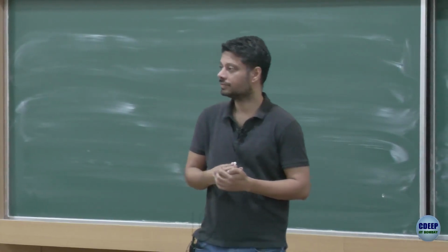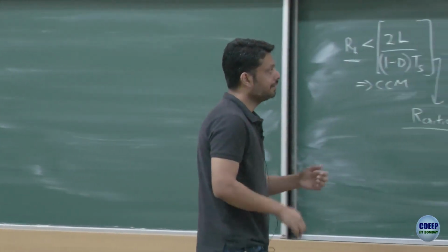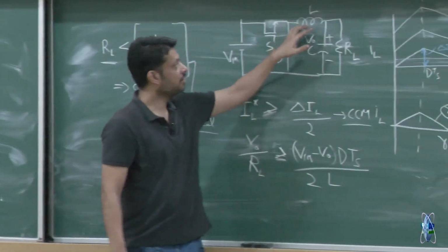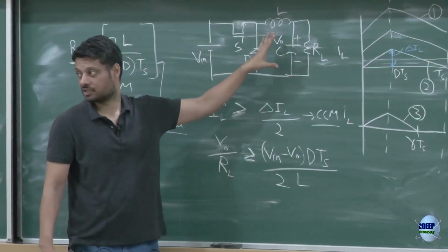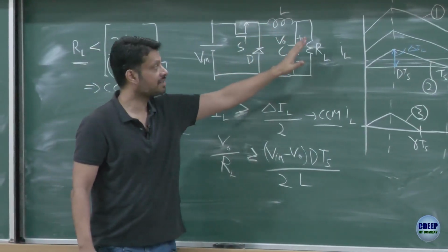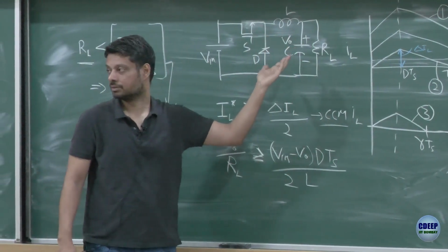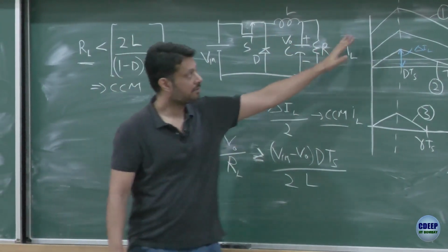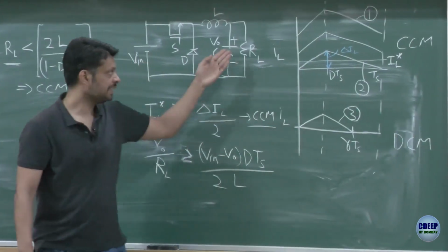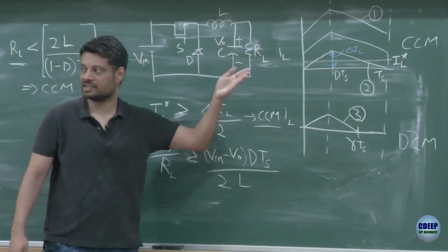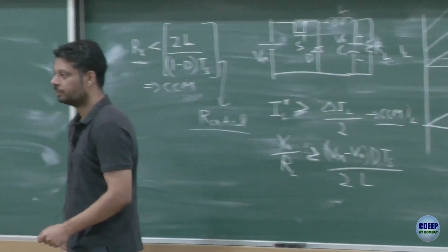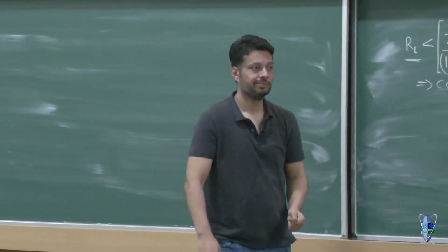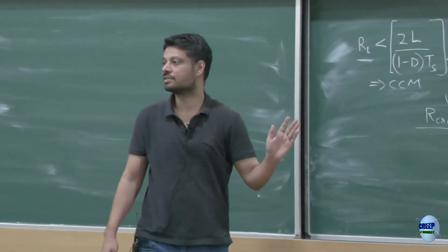No, that's what I am saying, right? Your converter is producing the voltage and the current is determined by the voltage. The voltage is constant from case 1 to case 2. You are changing the load resistance, current is changing accordingly. V by R. Any more questions?